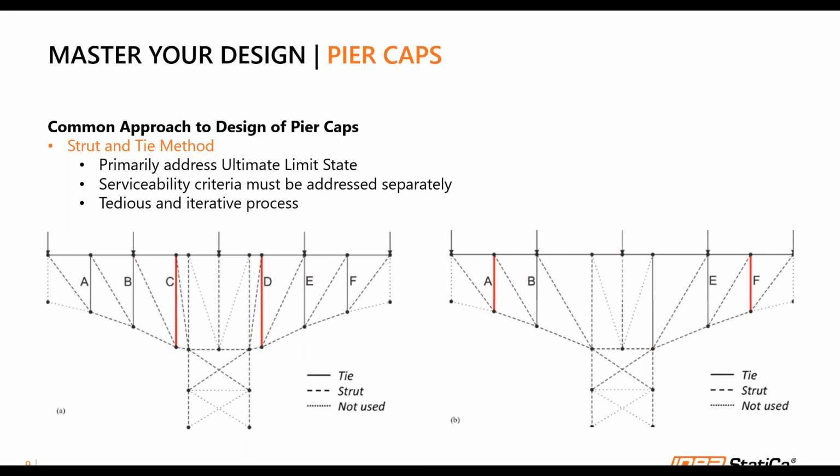And also you need to come up with multiple iterations just to get the perfect Strut-and-Tie model, which is time consuming. And to check also for serviceability criteria such as crack width, stress limitation, and deflections, you would need to address this with supplementary or complementary models together with the code provisions.